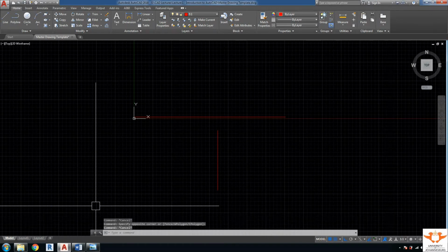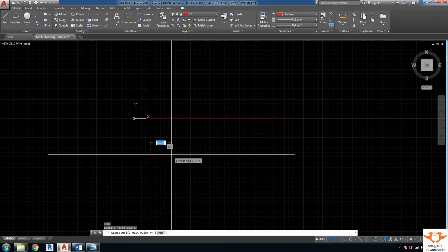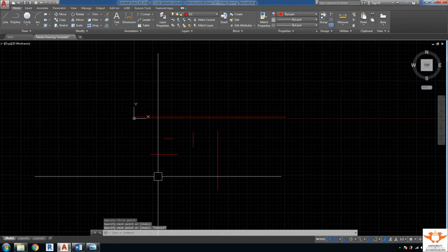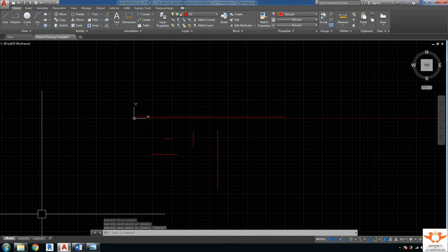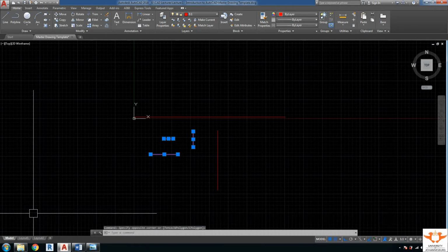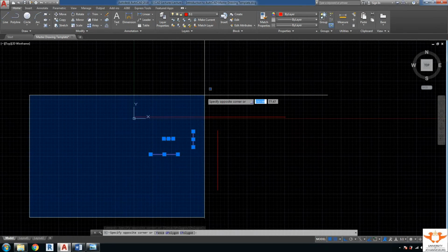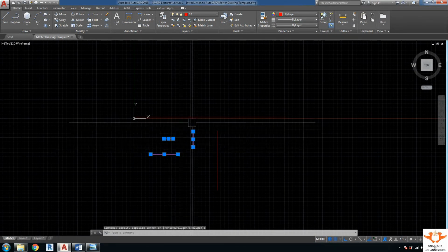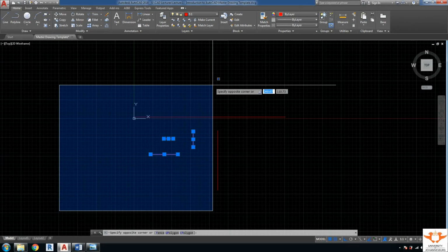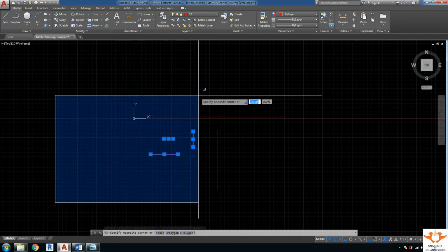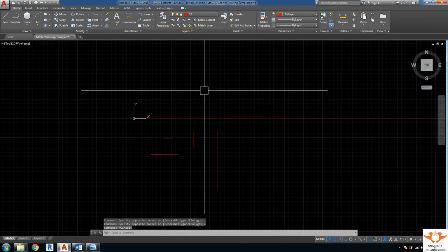For instance, if you want to select an object in your drawing, but you don't want to select all the objects, what you could do is start at the bottom left, coming up, and click. What this does is it will only select lines or objects that have two endpoints. So you find that AutoCAD has only selected these three lines because we selected all the endpoints, and it didn't select the longer line because we only had gripped one endpoint. So watch again. Very simple and very easy.